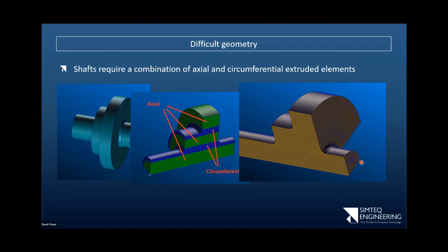And now I'm extruding it in the theta direction. This section again, I'm extruding in this direction because I want fewer elements there than there, so that the element size in that direction stays more or less constant. And I do the same for the last one as well. Okay, so this will result in both a significantly reduced number of elements and a significantly improved accuracy of the model, because the distortion level of the elements and the number of distorted elements are significantly less.